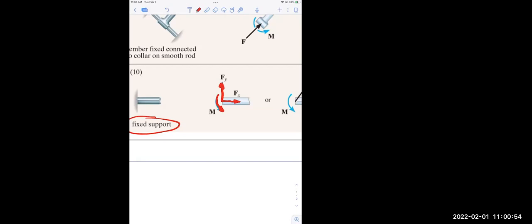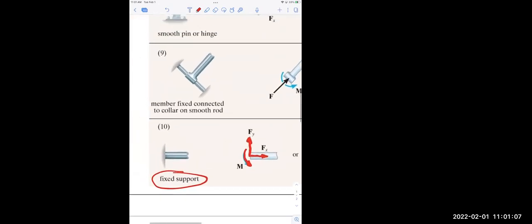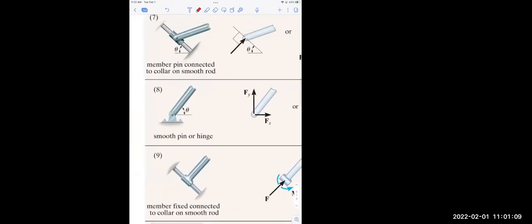So our free body diagram has always got to show all of the forces that are acting on something, and through equilibrium, we set those equal to 0. And so fixed is an important one. It's pretty common, and it's got 3 different forces, and I've got to think about all of those. Whereas look at this second one. This is another classic one.